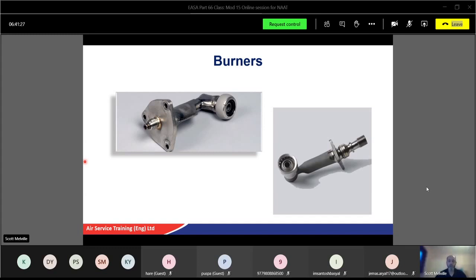All right. So again, you're also checking for cracks. Very important. If you get a crack on the body of a burner, you see where the welds are, you know, they're weak points. And through time, they can potentially crack anywhere on the body part. Okay, so again, anything that looks wrong, hot spots, discoloration, potential cracks, will need to be replaced or such like.